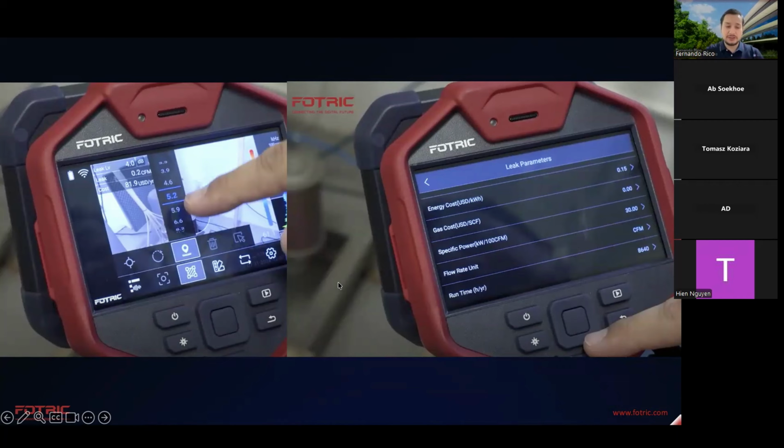And then on top of that, distance, that's why you saw on the previous one, stand 15 to 30 inches from the leak. And then you will also have to put the pressure, okay? With FOTRIC, all you have to worry about is the initial setup before you start, and then only the distance, because sound drops over distance. Now you can see the leak, which is 5, 10 feet away. You put the number, and the leak will be estimated considering that distance.